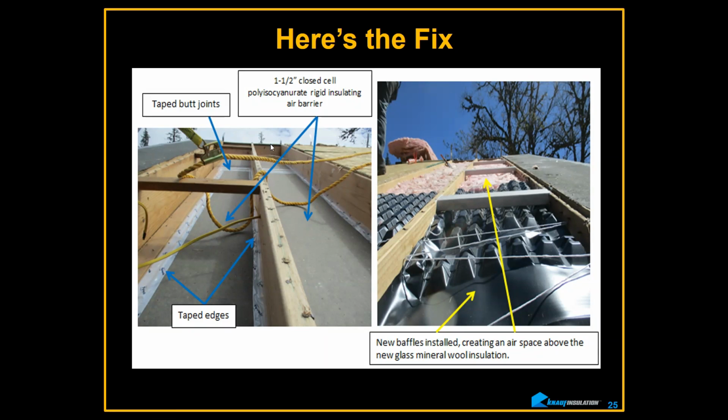But you gotta have that airspace. I can tell you that even though the code says 1 inch, some of them may say 1.5 inches, it's not enough. You gotta have 2 inches for it to work. Whether that's practical or not, that's another story. But you gotta have 2 inches for it to work properly, unless you're really good at 1.5 inches.